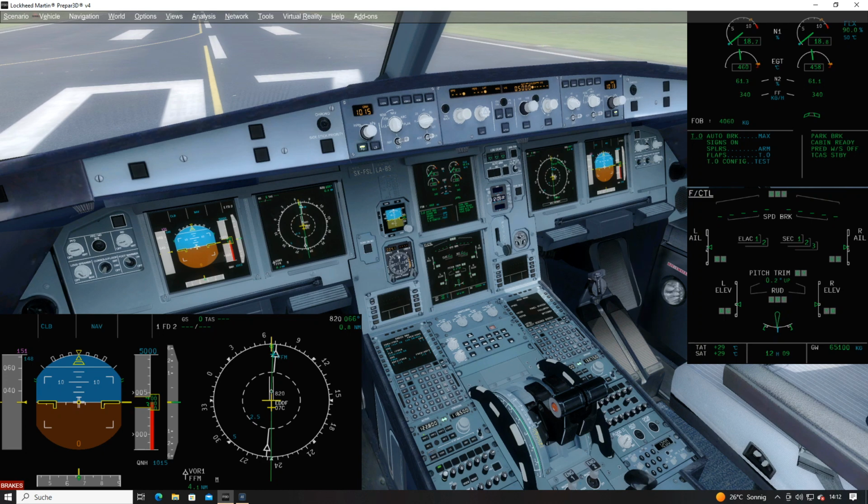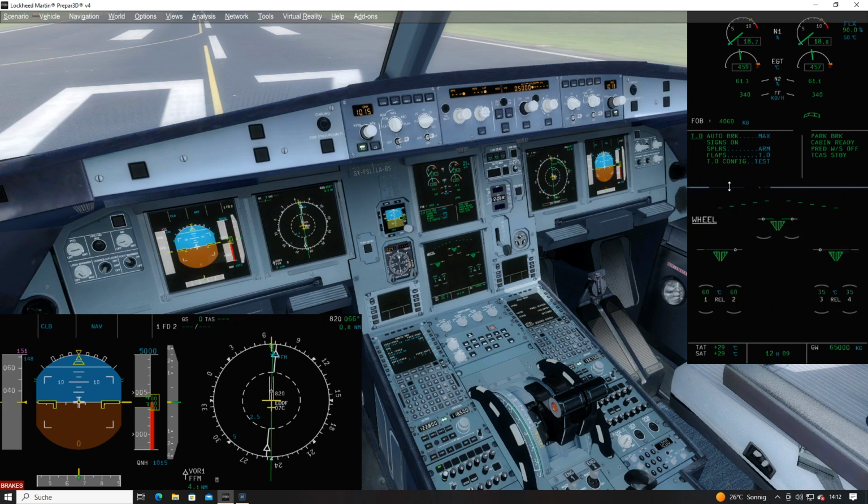You can see on the FO side, on the right hand side, how I can steer the rudder and also ride the brakes. So everything is set up. On the system page, on the engine warning display, we have the takeoff checklist. It's an automatic checklist triggered after a while. Otherwise you can trigger it with the takeoff config test button. However, we're still not in the correct configuration.